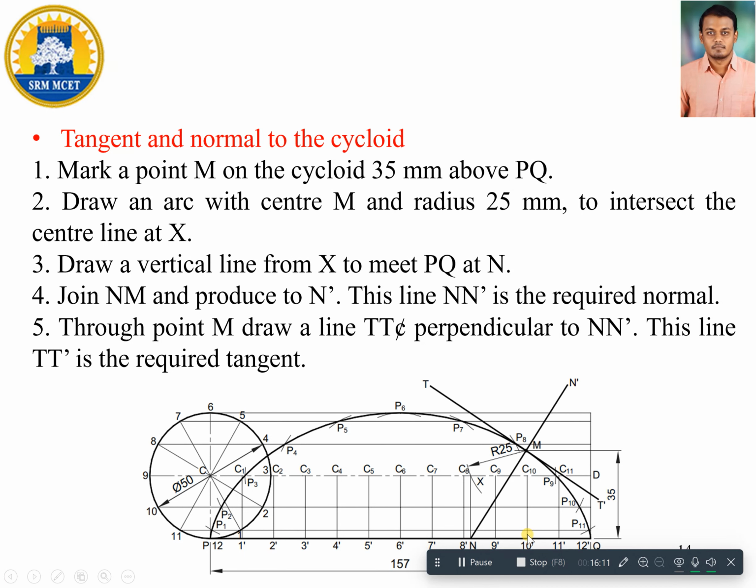So if you are able to use your common scale, move it very smoothly without compromising on the perpendicularity from the base, and if the 0 is at the base, here it should be 35 mm. So mark that point as capital M. So while we are measuring this distance, it should be equal to 35 mm.